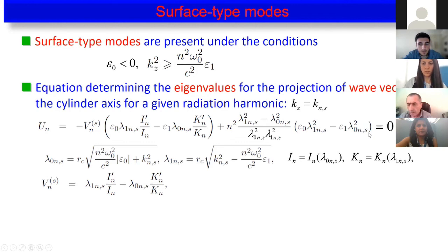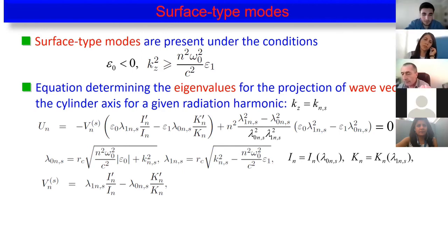get this equation? This equation is obtained when we evaluate the electromagnetic field. We evaluate the Fourier image of the field. Fourier image has poles as a function of complex variable kz. And these poles are zeros. These poles are the solutions of the eigenvalues of the dielectric cylinder. This means that this equation, in fact, determines the poles of the Fourier image of the electromagnetic field. These are the eigenmodes of it.